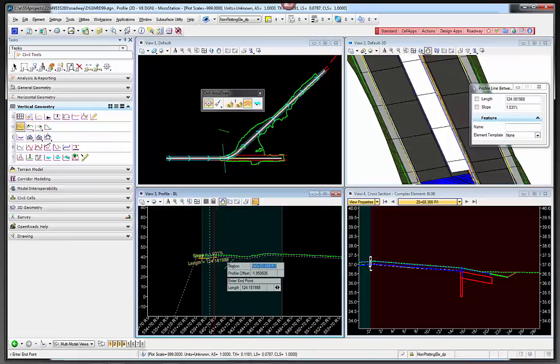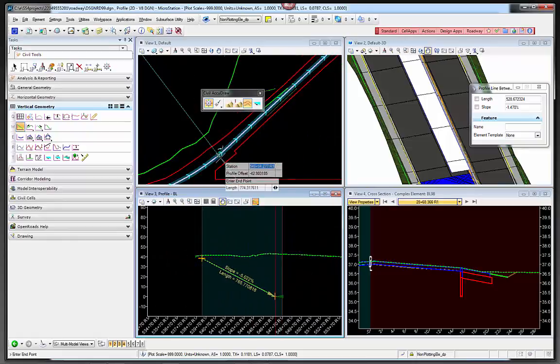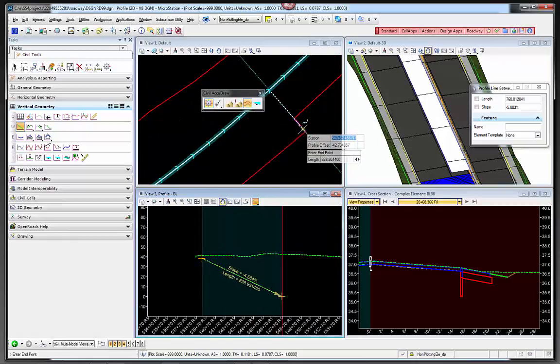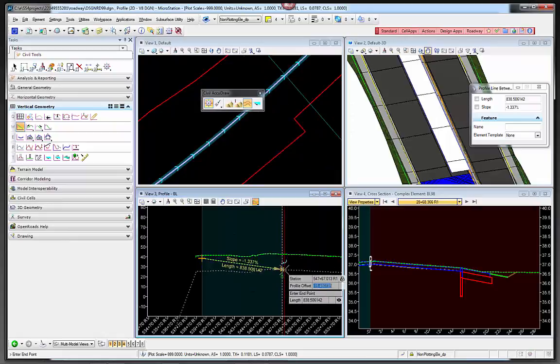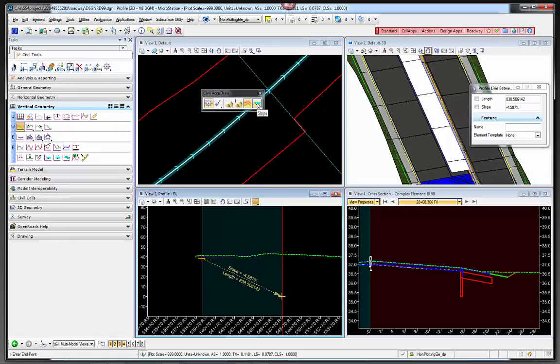Now I could do the same thing. I could just come in and find a station. Let's say there's a station in my plan view right here that I need to snap to. If I snap on this point right here and hit the Enter key, it locks it in the plan view for me. And then as I zoom in here, I'm still on this offset. So if maybe I wanted to do a slope from this other point, I could set the value now to slope and tab down here and say this is supposed to be a -1% and lock it. That would automatically draw that profile line at a 1% slope from the other one, and the actual PVI is right at the station at this horizontal location here.